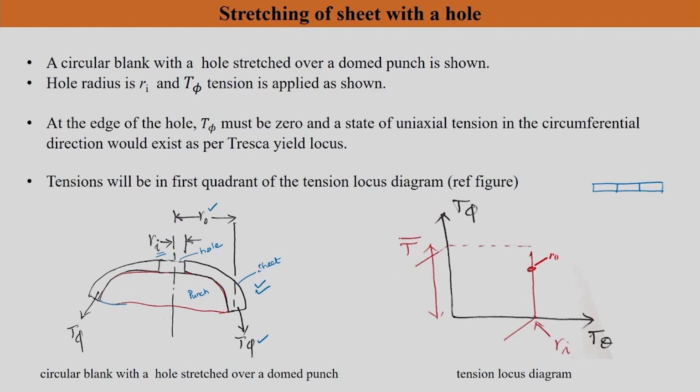So, what we are studying is applicable for the hole expansion test. The hole expansion test, I think we already discussed in the formability chapter. Basically, it is a formability test which will tell you the deformability or formability of the hole, of the entire sheet along with the hole.